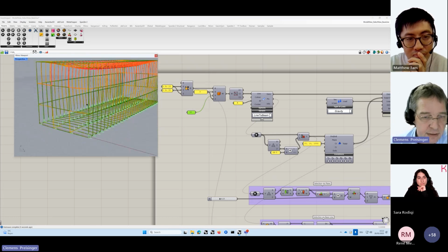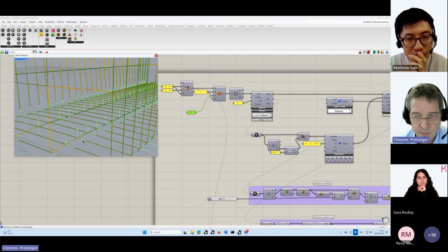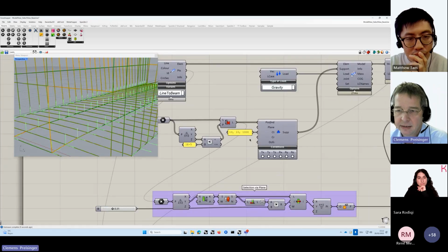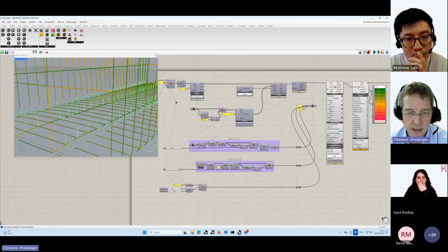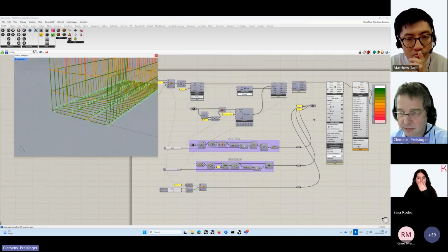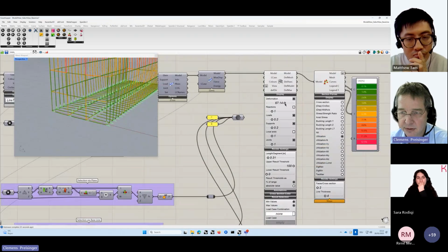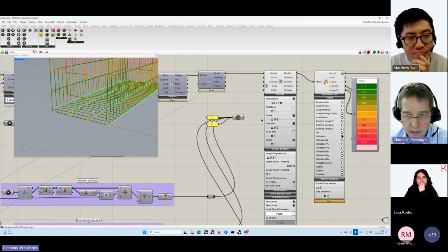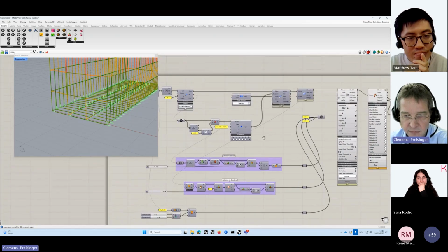And here you can see the new support option, namely that it's now possible to supply a translational spring stiffness or rotational spring stiffness at the support. And this can be used then to simulate the structure-soil interaction. For example, you see here now that the supports also move a little bit because they're not infinitely stiff.